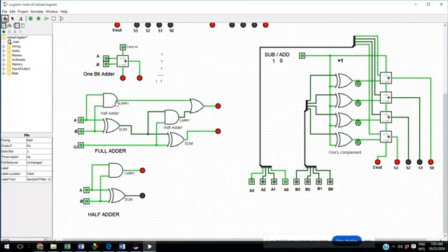We combine two half adders in order to get the full adder, as we mentioned earlier in the previous lecture. This full adder will accept 3 inputs and have 2 main outputs, the sum and the carry, as you can see there. If we set them back to 0, 0, 0, then the sum is 0 and the carry is 0.